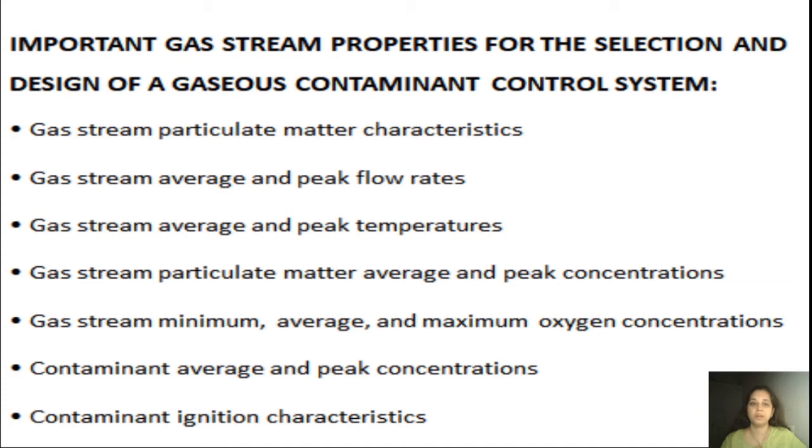Both of these play a very crucial role because when the system is being designed, if there is excessive particulate matter present, or the particulate matter's characteristics are such that it would be reactive, corrosive, or quite minute, it could probably cause clogging or certain kinds of reactions in the system, damaging the control system.